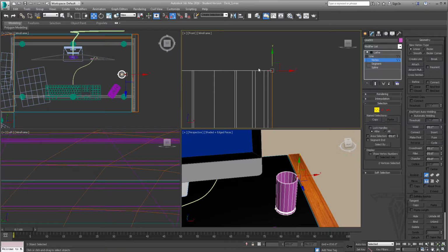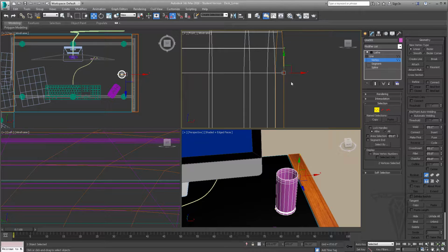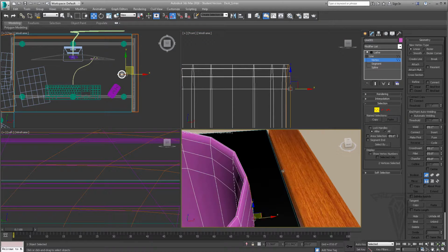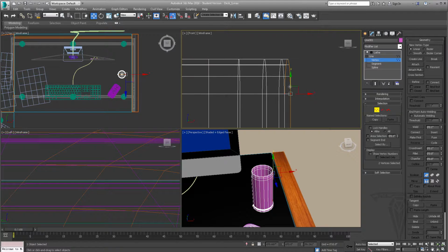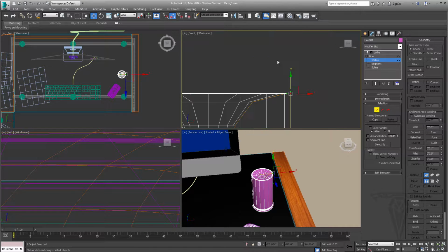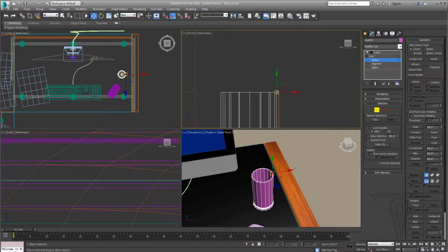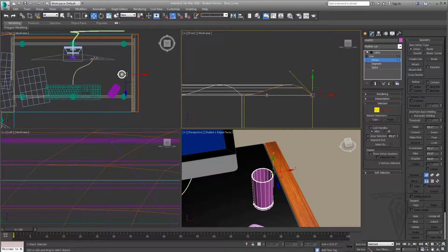And the lip, let's actually go ahead and select these two vertices and see what happens when we add a smooth. Okay, that's too much. So let's undo that and right click and say, let's say Bezier. No. Let's go Bezier corner. So then I can play with these manually. I'm going to grab this tangent line and this tangent line.